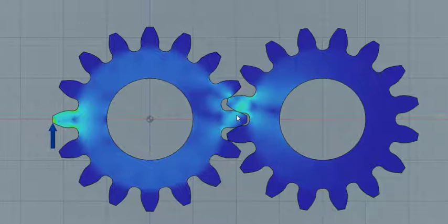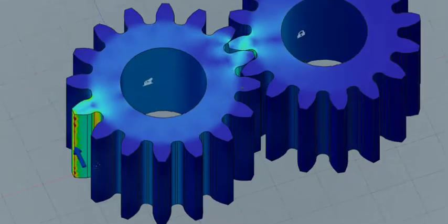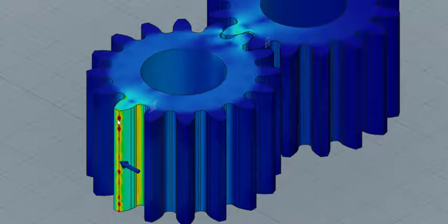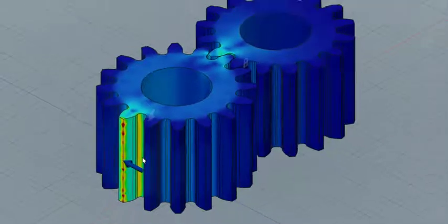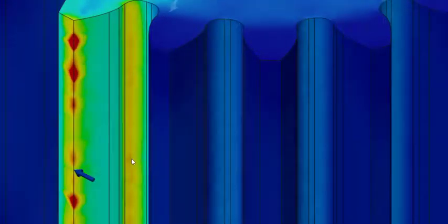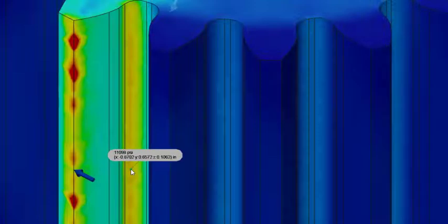I did this so we could compare the direct bending stress on the tooth loaded at the tooth tip to the stress that is occurring in the gear teeth that are meshed. You will notice that on the gear tip, you have to ignore the location of the applied load because that tangential load is going to generate very high stresses. What we want to do is look down here at the fillet radius at the root of the gear, and you can see that the stress is rather large at that location. And if I do so, you'll see on the order of 11,000 psi at the root of the tooth.